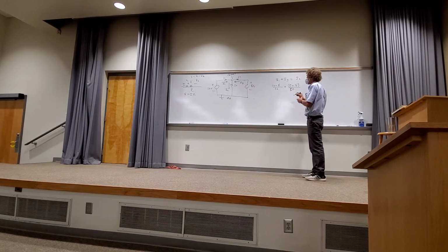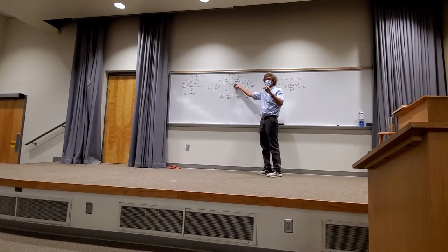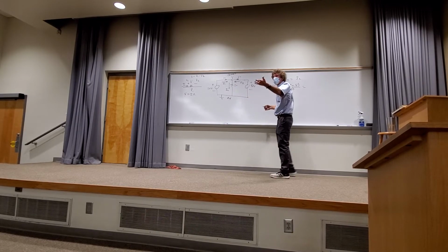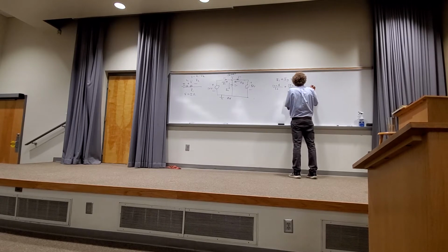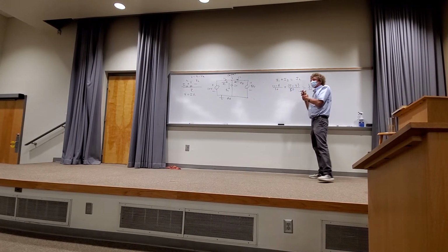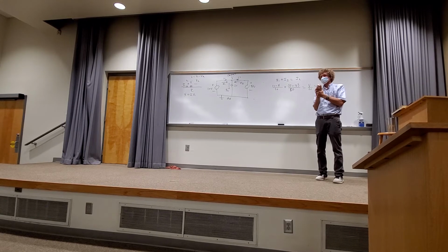And that equals I2. What is I2? Anyone? Voltage on this side is V. Voltage on this side? 0. We don't have to do the 0. Who cares about 0? So it's just V over 20, right? Now that's one equation with one unknown, isn't it, guys? We can solve for V very easily, right?